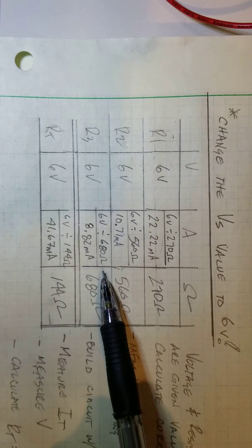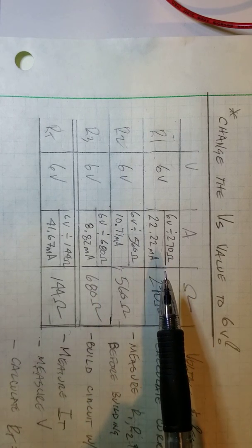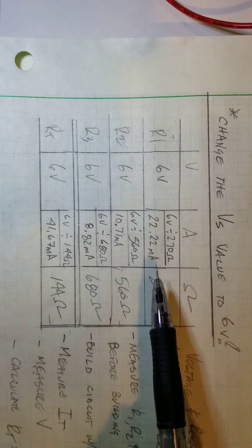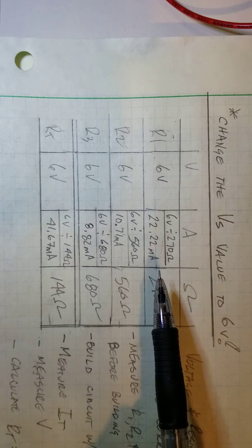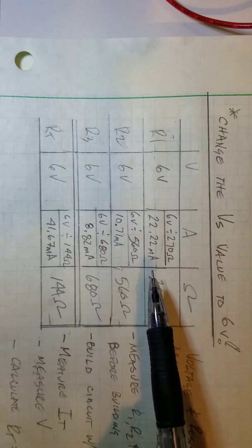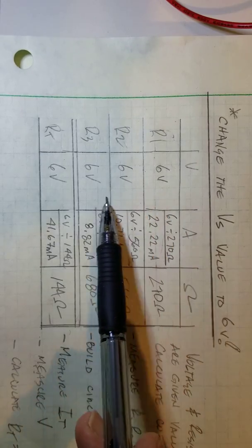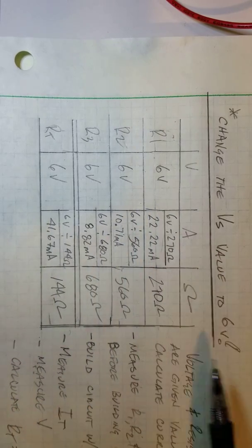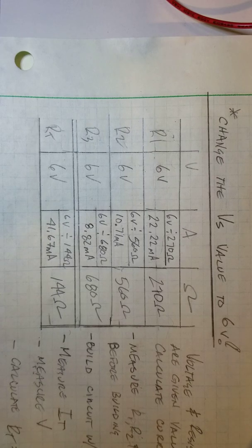And so one of the things we need to recognize about these parallel circuits is that the branch current is independent of any other branch. So what happens to that branch doesn't matter what happens to the one beside it, to the left or right. If it's operational, it will get the current that it needs across it. We're going to apply 6 volts just because I have a 6 volt battery as my source here. And we're going to build this circuit and take a look at that.